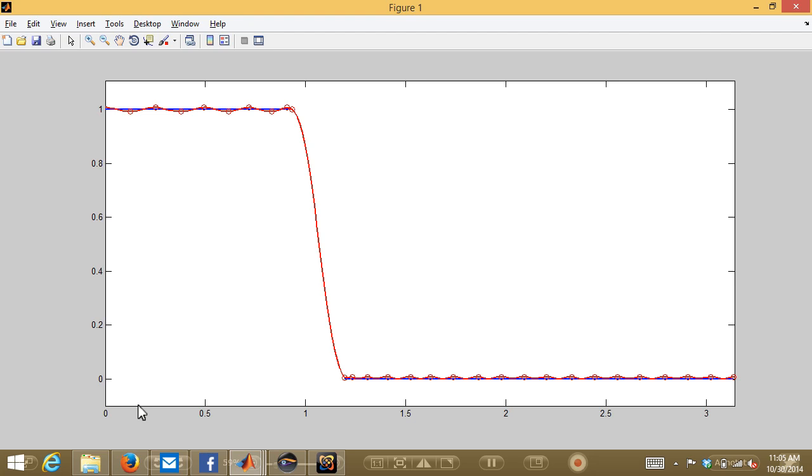So filter design is a lot like this, where you say, okay, what am I willing to tolerate in terms of filter length, ripple in the passband and stop band, and width of the transition region, right? You can't get everything all at once, but you can get 3 out of the 4 is the idea.